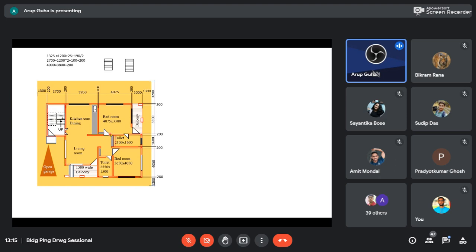What is happening here? The door will swing this way. So hinged over this place, and when we close the door, that actually comes or revolves and settles over here. So we can draw a quarter circle, or for ease we can draw a 90-degree angle. Means this arm and this arm should be the same. Instead of putting a circle, it means actually this opens this way. So this you will have to think of.